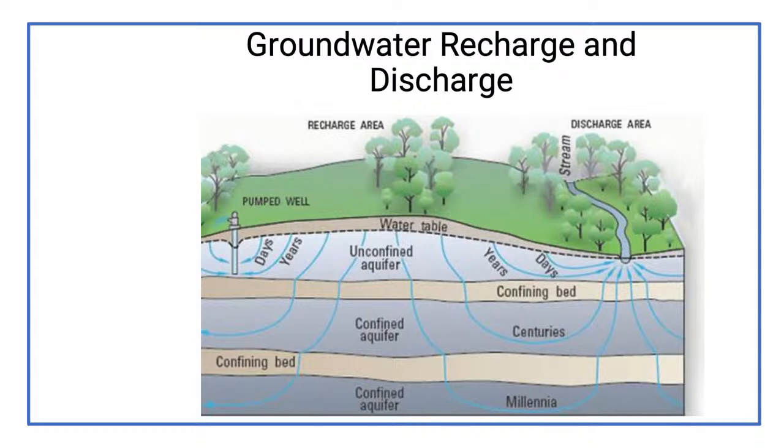The groundwater recharge and discharge, this is a hard concept for people to grasp. Is water actually flowing upwards to streams? But what water does is it flows from zones of high pressure to low pressure. Generally, we think of gravity coming into play, and that's generally true. It is going to be gravity driven. So water flows downhill, but to water in the ground, downhill can actually be the water appearing to move up because it's moving from high head to low head, high pressure to low pressure.